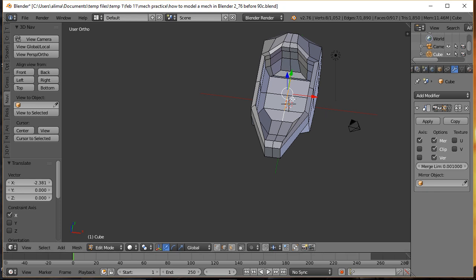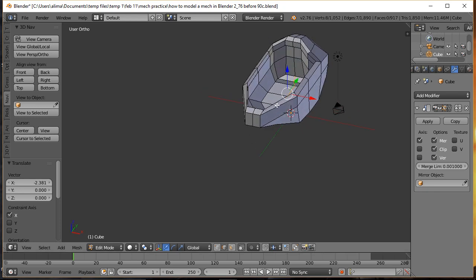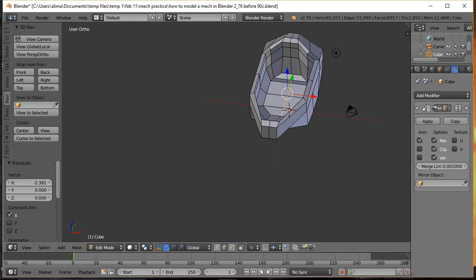Because of this clipping, you can see the geometry basically looks like it kind of sealed itself, which is good. One thing to keep note of is when you use geometry with a mirror modifier and you push geometry towards each other to create kind of like a seam like this, typically what happens is you have extra vertices, and those will cause issues.